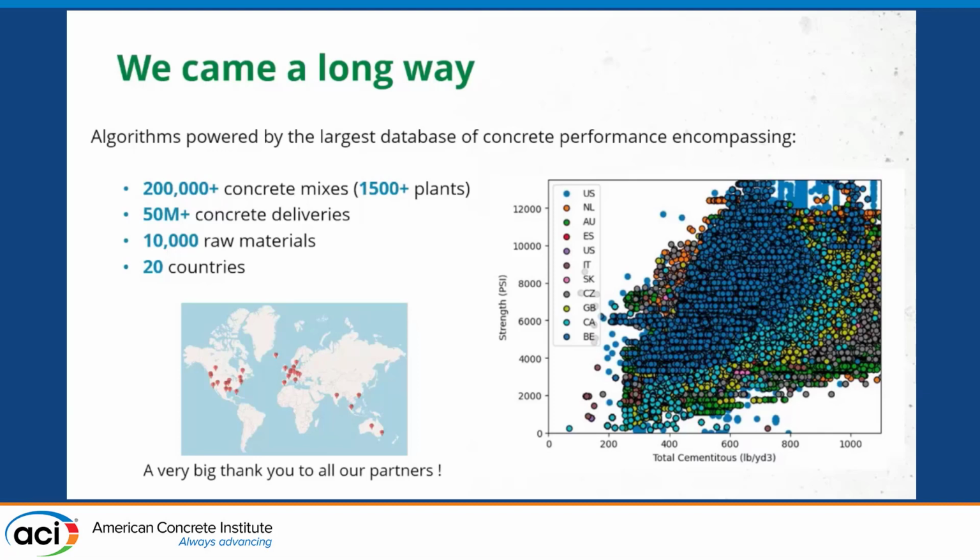For example, if your aggregates are right there versus shipping them, your mix is probably going to be a bit more weighted on the aggregates because they're coming from right there. So each material does have a CO2 impact, and depending on what you want to optimize for, the tool does provide you a mix design in accordance with what's either cheaper, more expensive, or more CO2 versus less CO2.